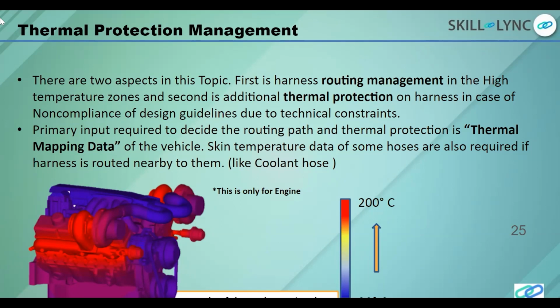So we need to be careful with how the routing is done in this area. We are going to use high protection devices like cotton tapes as well as nylon tapes and silicon tubes, sorry, which we use in those particular areas so that we are able to withstand temperatures in excess of 900 degrees Celsius. The silicon protective coverings can withstand temperatures in excess of 350 or 330 degrees Celsius and above. So we need to understand that we have thermal management data before we do the routing.